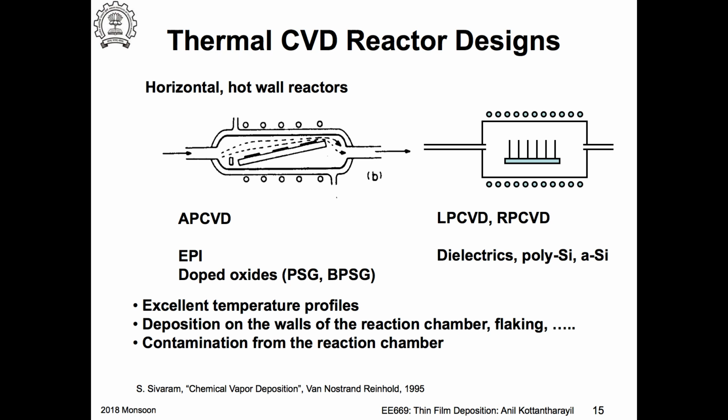Typically these furnaces are made using quartz, silicon dioxide. Let's say I'm going to deposit silicon nitride. As the thickness increases, these are two different materials, and the film that is already deposited is seeing, let's say, 800 degrees for 4 hours today, and so on for 3 years. So for a very long time, it was at 800 degrees centigrade.